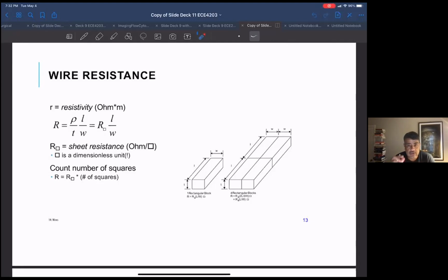The thicknesses of the printed circuit board stack, I'm assuming you've all seen printed circuit boards, are fairly thick. So the resistance and capacitance on a printed circuit board aren't that important, but inductance starts being much more important, because the lengths are longer and it's important to control the inductance. Anyway, just for your information, but on chip, we're really worried about resistance and capacitance.